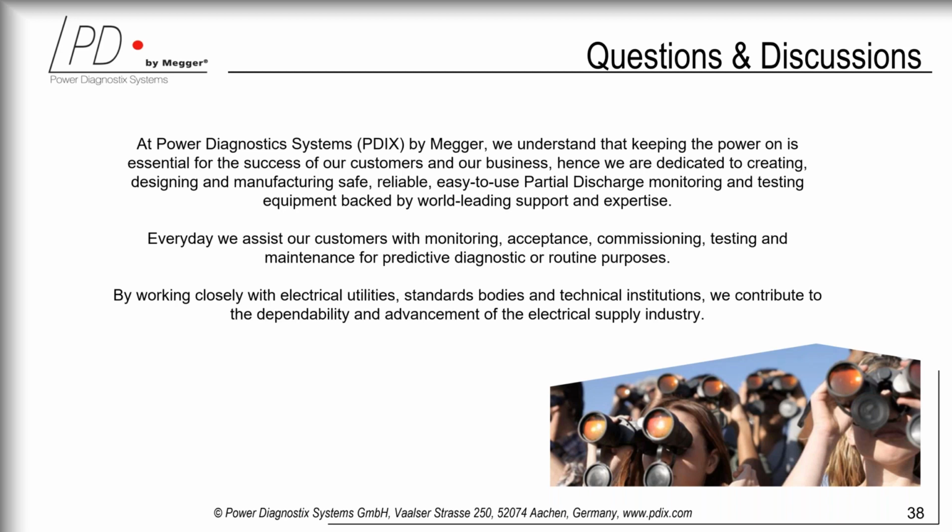Okay, so this is a very interesting question. The reliable diagnostic is obtained very quickly. Even in factory acceptance tests or otherwise, after setup, which can take hours, a test of about 2-3 hours will clearly give us a diagnostic: do we have PD, and to what degree and where, and so on. That can be done both online and offline. The question is, how long should we monitor?